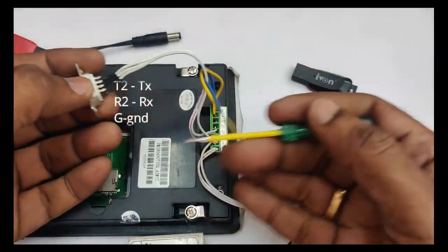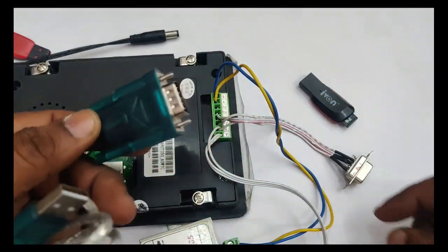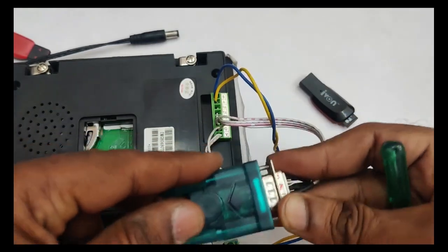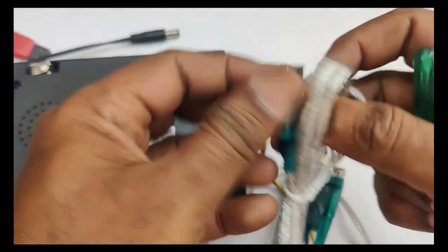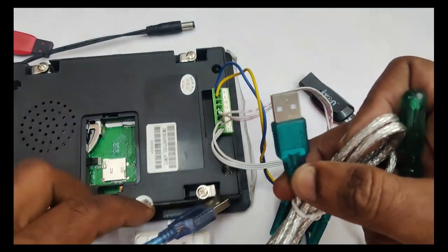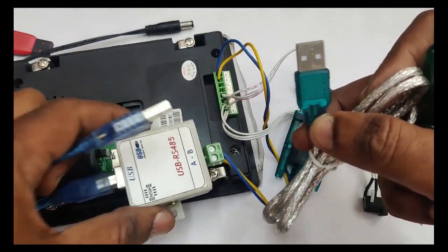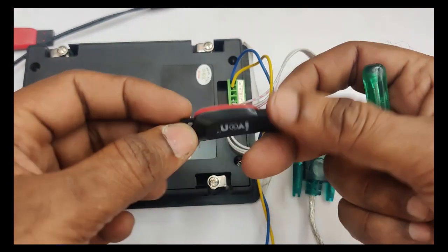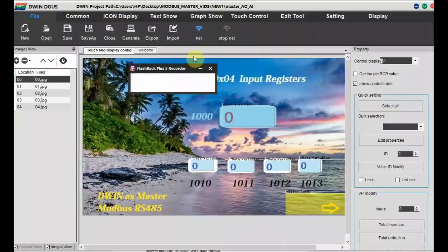connector. This is just to download only the 22.bin file, as we have to modify the 22.bin file often. We will be using this connection. An RS232 to USB connector is used in this method, and when connected to the PC it will also offer another port number. Through this we will be downloading the 22.bin file. Other project files will be downloaded using the SD card method.